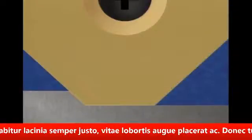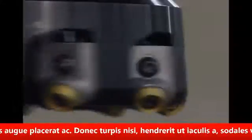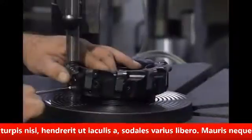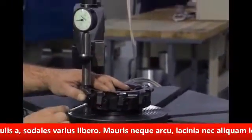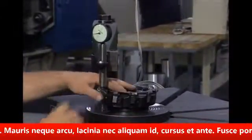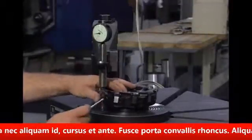A large corner radius produces a finer finish than a small radius, but a corner wiper flat on the insert produces the finest surface finish. Sometimes a single wiper insert in a cutter will improve the surface finish, even if all the others are roughing inserts. For best surface finish and longest tool life, all inserts must be preset to carry an equal load. One or two inserts protruding further than the others will carry the cutting load and wear out prematurely.